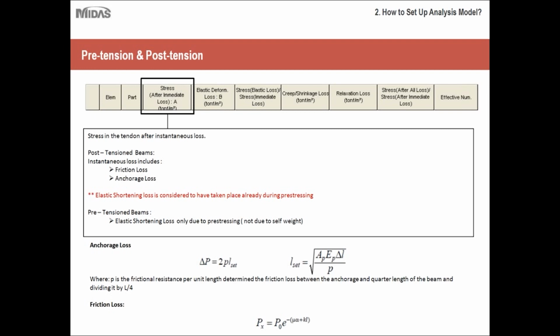Depending upon the type of tensioning you are applying, whether it is pre-tension or post-tension, there will be different types of losses. So it is sometimes really hard for any software program or for engineers to consider these losses separately. What they do is either they lose track that it was a pre-tension tendon strand, and they compute the post-tension tendon losses. So there's a lot of scope for human error that keeps all the engineers on their heels.